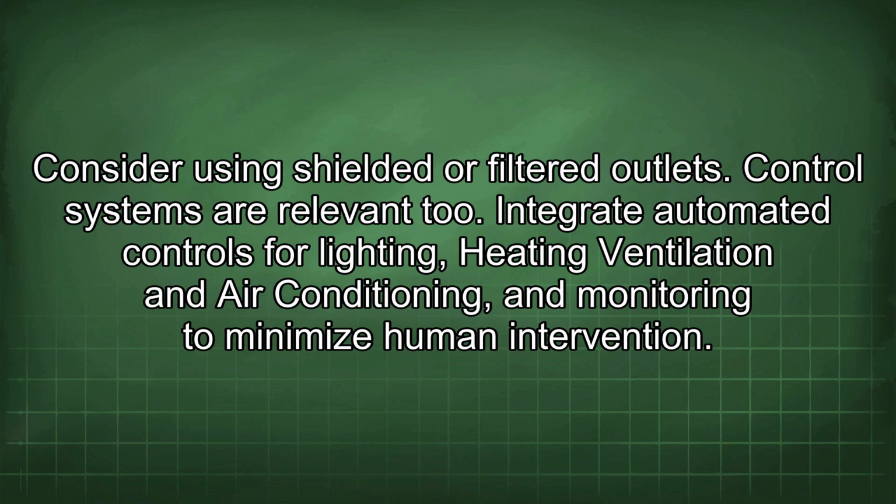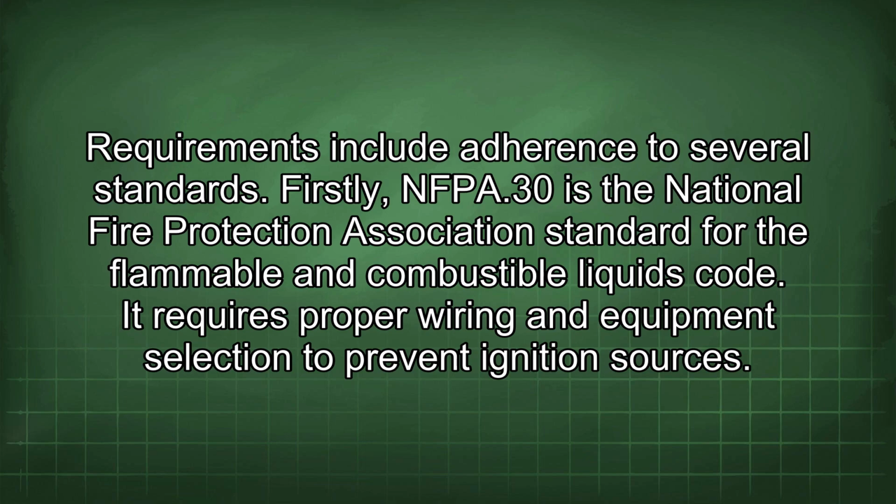Control systems are relevant too. Integrate automated controls for lighting, heating, ventilation, and air conditioning, and monitoring to minimize human intervention. Requirements include adherence to several standards. Firstly, NFPA 30 is the National Fire Protection Association standard for the Flammable and Combustible Liquids Code. It requires proper wiring and equipment selection to prevent ignition sources.